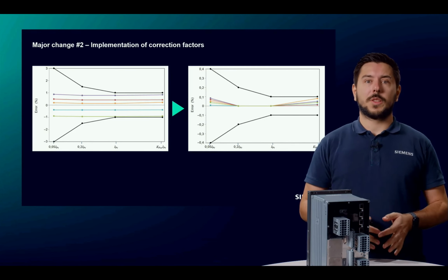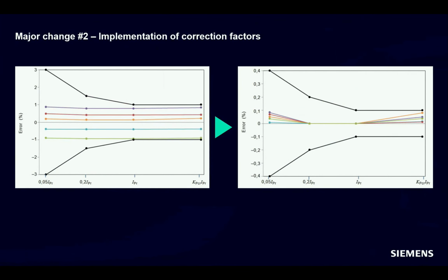The second change concerns the technical data of the sensor. There is a fundamental difference compared to conventional current and voltage transformers. The standard, especially IEC 61869-6, explains how to determine the accuracy class of low-power passive current transformers by using a factor called CFI, where the I stands for current. This method is an improvement over the traditional approach of using the rated transformation ratio to define the accuracy class. The key advantage of using the CFI is that it allows for a higher accuracy class designation for passive LPCTs.